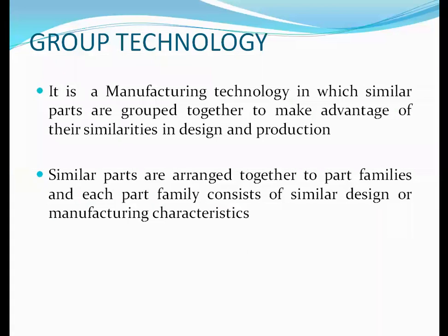Group technology is a manufacturing technology in which similar parts are grouped together to take advantage of their similarities in design and production. For example, say there are around 100 components. Out of these, on 10 components we have to do the turning operation, and on some 10 components we have to do the drilling operation. Here the operation remains the same for the 10 components. So in group technology, we identify those components and group them together.